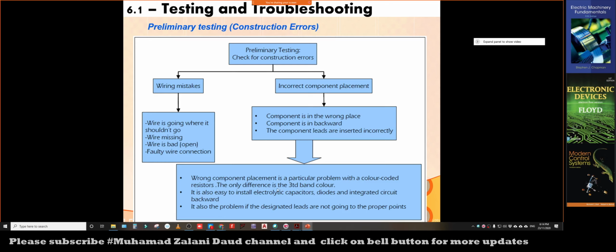And then some color-coded components like resistors, we can easily make mistakes. For example, a 1 kilo ohm resistor, when that place is supposed to be for a 10 kilo ohm resistor, but we wrongly read the color code of the resistor, then we accidentally place the 1 kilo ohm.